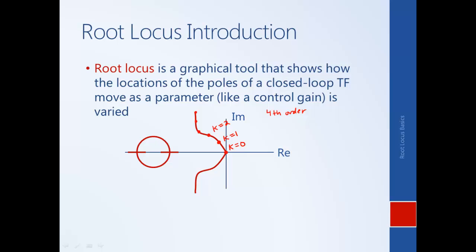And by knowing where the poles are, we can figure out which poles are dominant. We can figure out are they indicating that the response is getting faster? So moving the poles to the left in the complex plane corresponds to making sigma larger, which corresponds to a faster settling time. We can see what the effect is on beta or zeta to get a sense of overshoot, things like that. And so this is very helpful for higher order systems because we don't have these precise algebraic relationships.